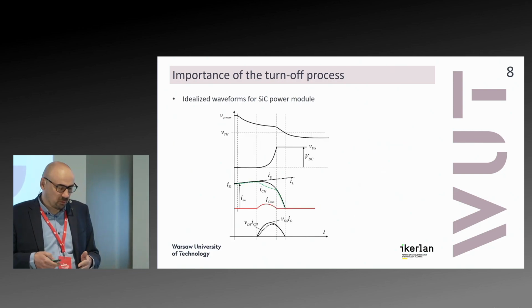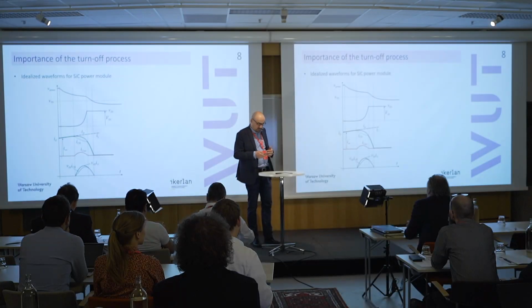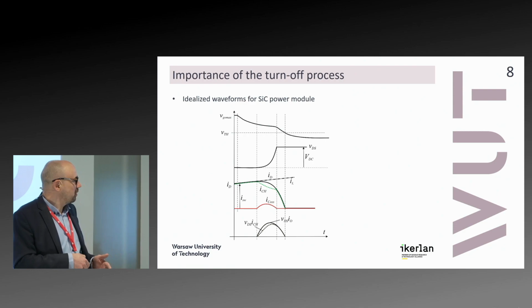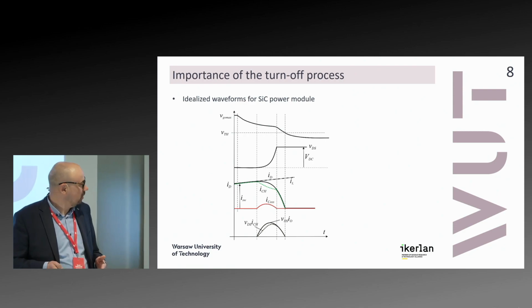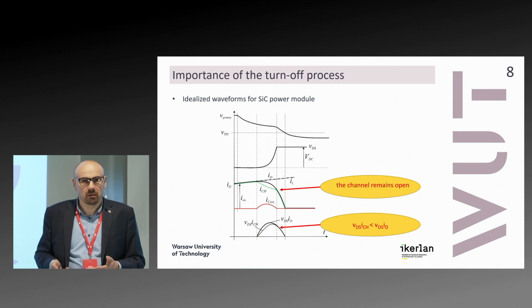So basically, for the power module, typical waveforms look like that. We have the voltage rise and the channel current here, and after that, when the voltage reaches maximum, we still have some remaining current here. And of course, you can see the difference in the waveform. So basically, what we did, we've been trying to find and identify the channel current to recognize the real or actual loss.